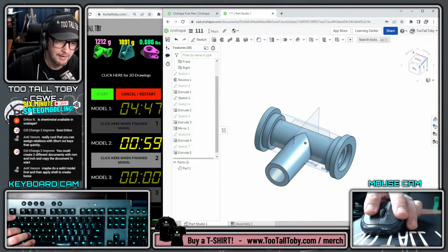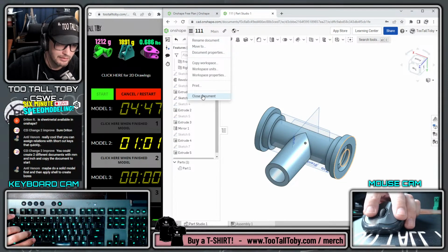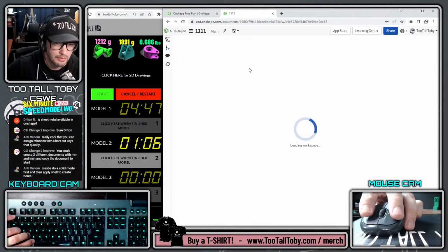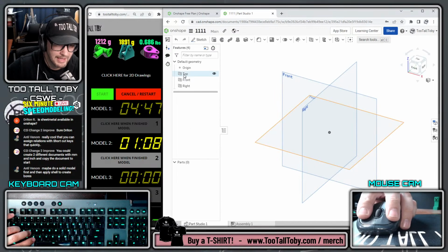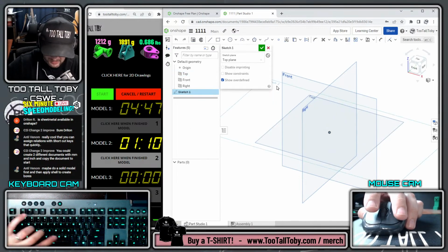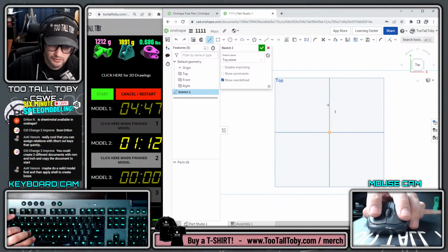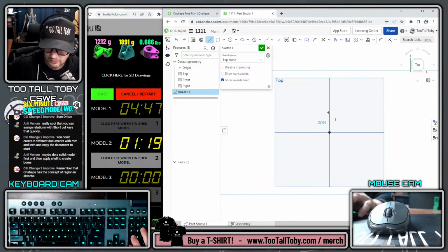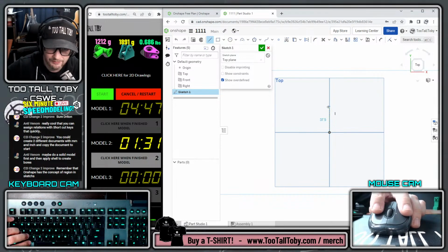It's almost like I could do top plane, begin a sketch, get normal to, and then create. See, I still want the solid. I want the solid in the middle for the cut extrude later. Concept of region and sketches. Yeah, I know. That's a great bit of advice that you're giving me there, Eduardo.